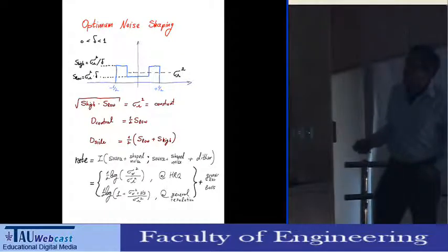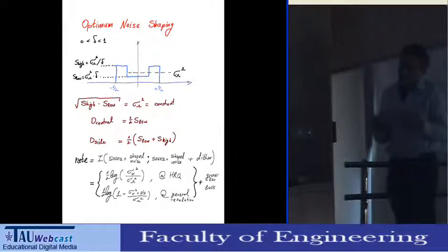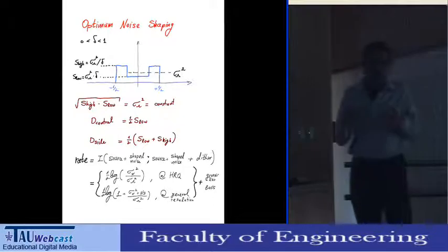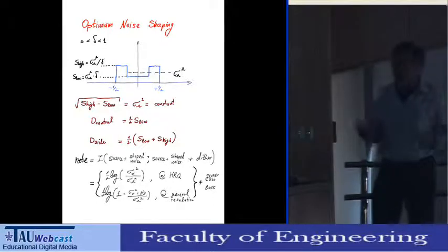It turns out that the product of this height and this height is fixed. This is the second moment of the quantizer, which is a lattice quantizer. This is why I denote it as sigma lambda squared. The product is fixed, and the ratio between these two heights determines the ratio between the central distortion, D0, and the side distortion, D1 or D2.